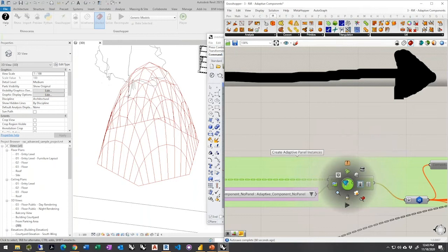By creating the adaptive component with these parameters, and to be clear, they'll need to be instance parameters, I'll be able to modify them after I create them through Rhino.Inside.Revit. I can also do that with material parameters. I can create a material parameter and assign that to an object within an adaptive component family, and then modify that parameter at a later time.